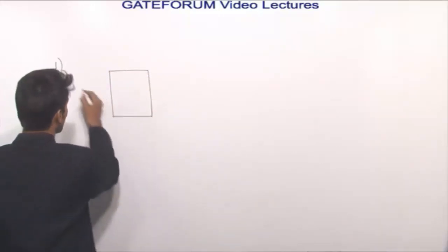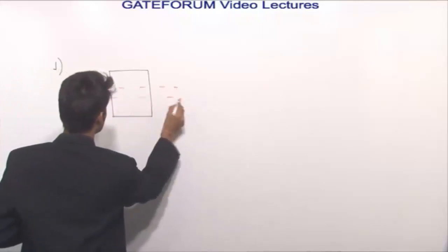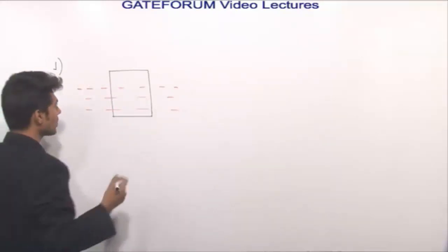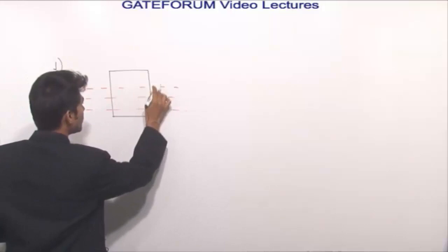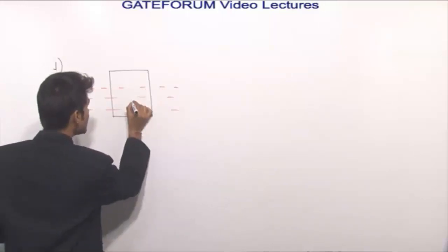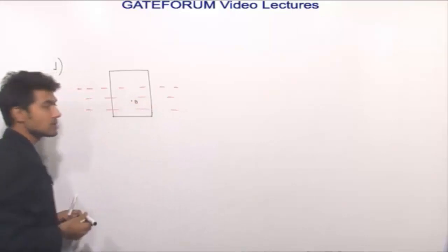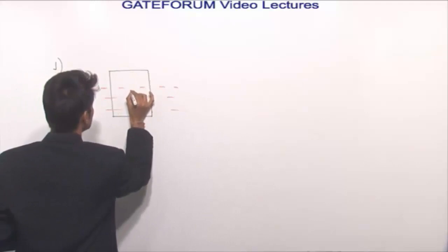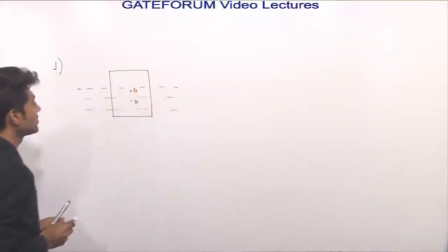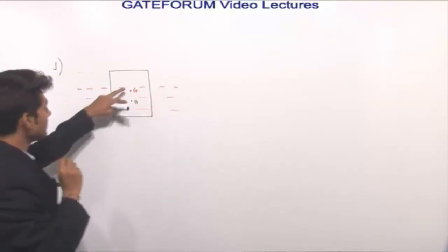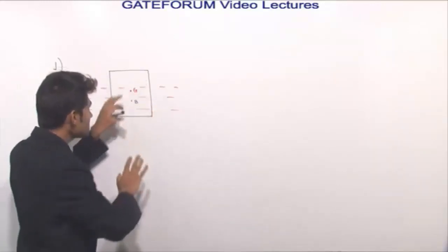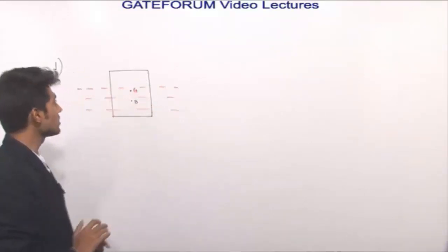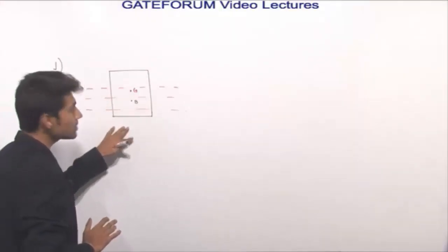If it is a floating body, then it will be immersed up to certain depth in the water or any liquid. Now whatever volume is displaced, center of that displaced volume is known as center of buoyancy. And for this particular body, if I am taking this body as a normal object, then center of gravity is here. In this particular figure, the statement 1 is clearly shown, like center of gravity is above the center of buoyancy. Now we will see whether this body is stable or not.